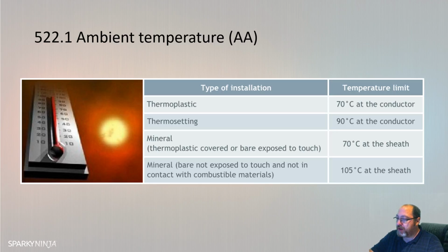Okay. Now, the classification of external influences is broken into three categories of external influences. We call them the general categories. They are A, B, and C. As you can see, A is environment. This is an environmental external influence. B is utilization. That's how it's used. Who uses it? How often it's used. And C is construction of building.